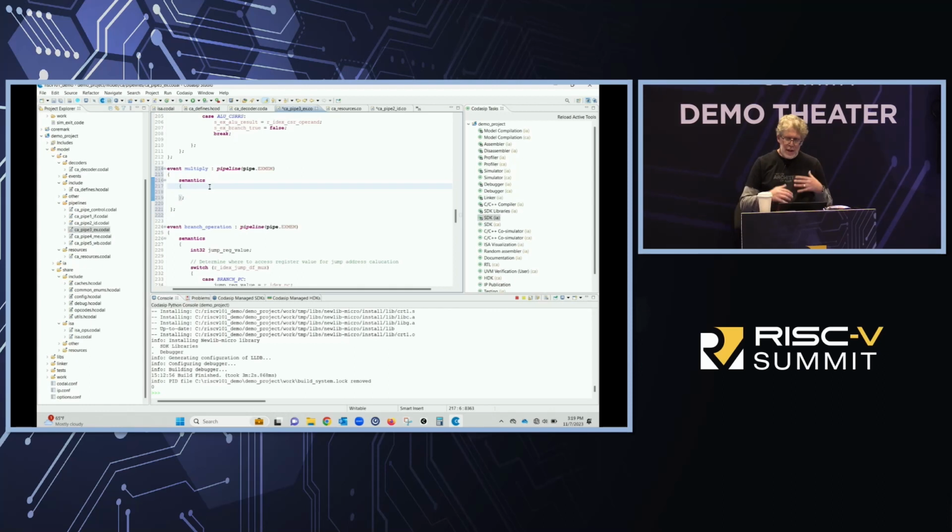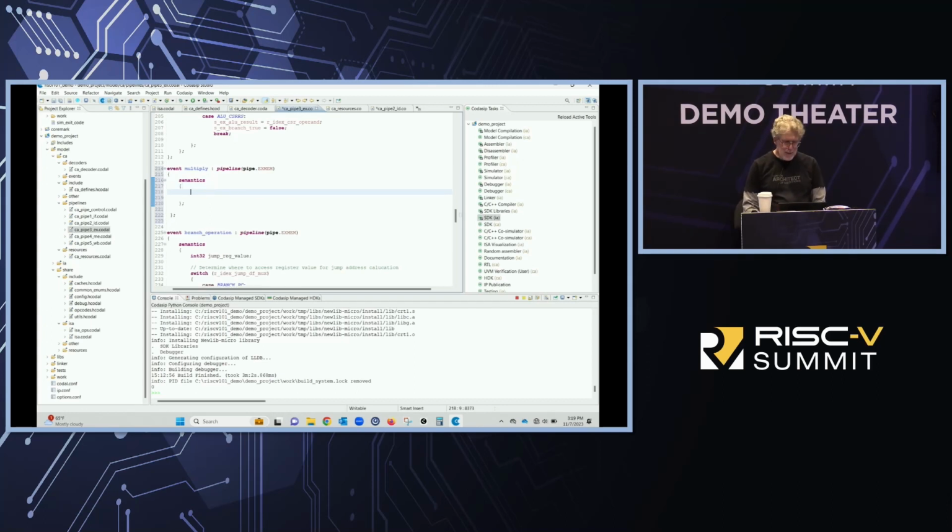If I fully build out this multiply compute element, for the RISC-V Zmmul or M extension I need 4 multiply opcodes. I'm only going to implement one for this demo, but I know I'm going to implement more in the future. So I'm going to use a switch statement like I did for my ALU.